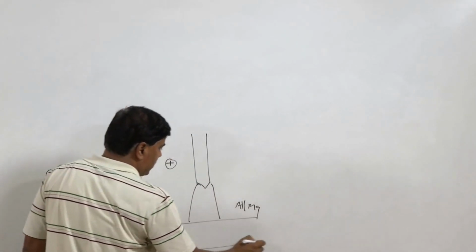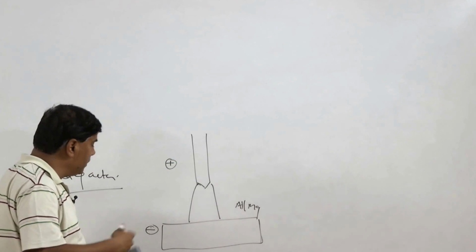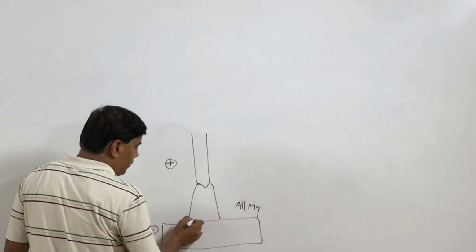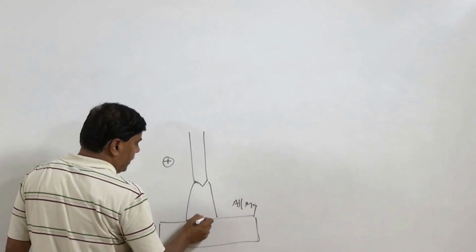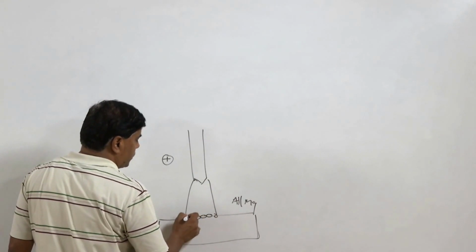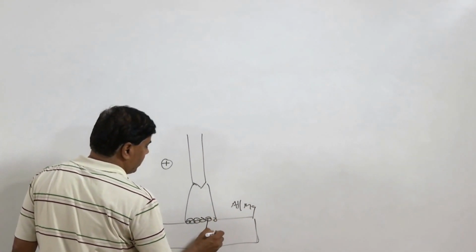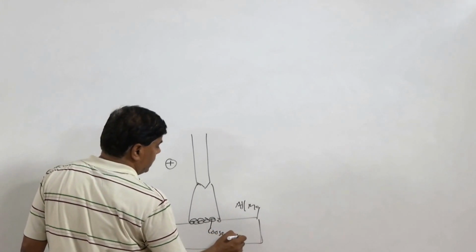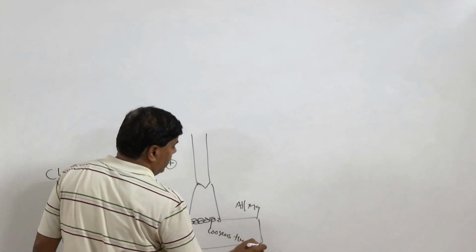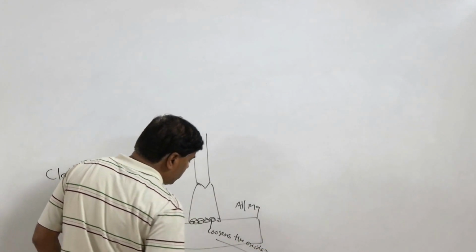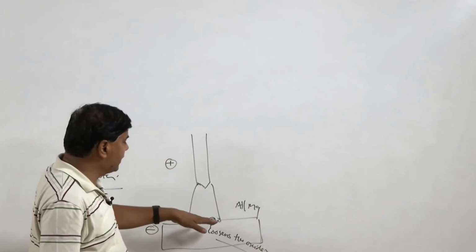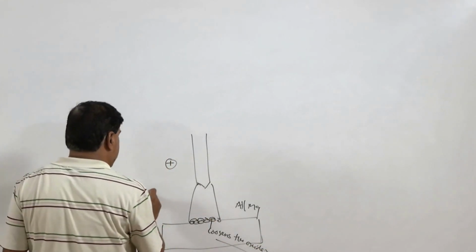In this case our workpiece is expected to emit the electrons, and if the mobile cathode spot is formed at the surface of the workpiece, the mobile cathode spot formation actually loosens the oxides being formed.